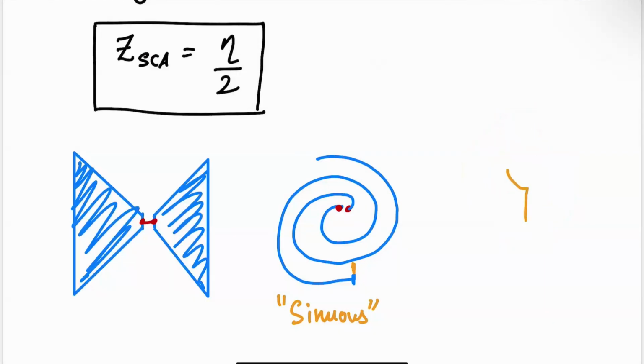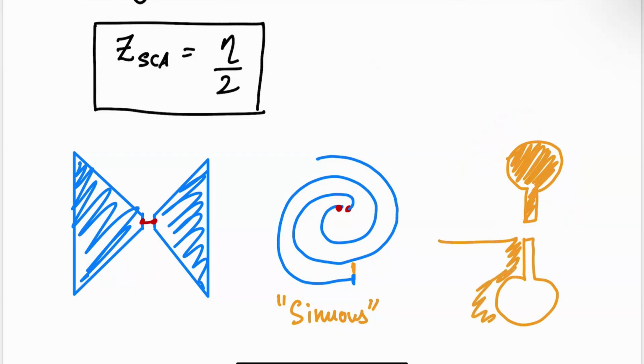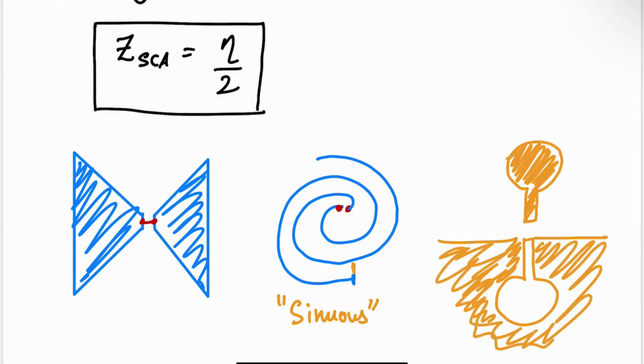So I can make a bulb like that. And I take the same bulb, make a copy on the bottom. And the top side, I make it metallic. Bottom side, I make the rest of it metallic, right? Like all of this is metal now, right? So this is called a top-loaded dipole. And that's another example. And so you can put an excitation across this like that.